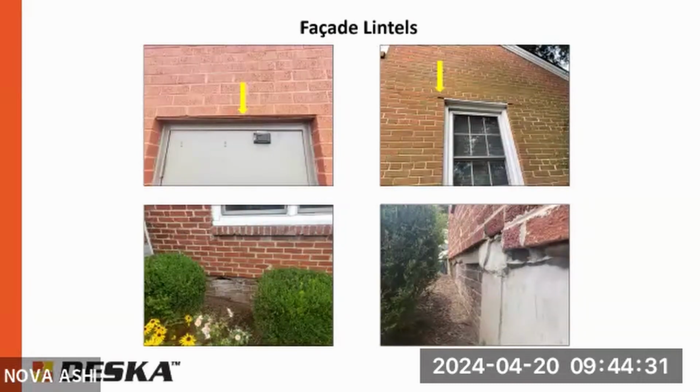And then typically it will cause the mortar joints next to the opening to crack. That's the beginning sign of that expansion, when the mortar begins to flake off on both sides of the corner of the window. It only gets worse unless you do something about it. In many cases, if you clean them and paint them and have it repointed, you can salvage them and you may be fine. But if they're unattended, once it begins to expand, that's usually about it, and they need to be replaced.